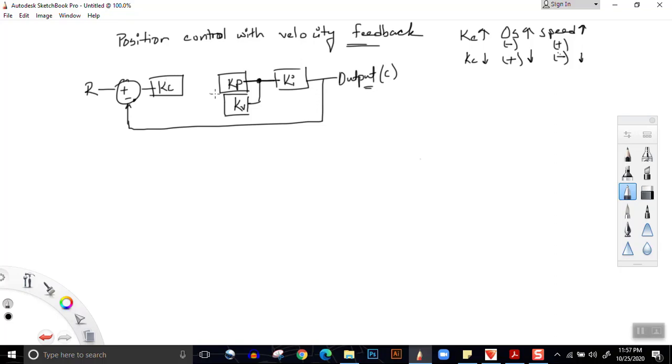The Kc will have an effect on the velocity feedback. But we do not want that, because if Kc has the effect, then these both conditions will not be improved, because the trade-off is caused by Kc. So Kc cannot have an effect on the velocity feedback. So we just put it here. Here plus, minus, and we have a velocity feedback here. This is how the system is supposed to work.